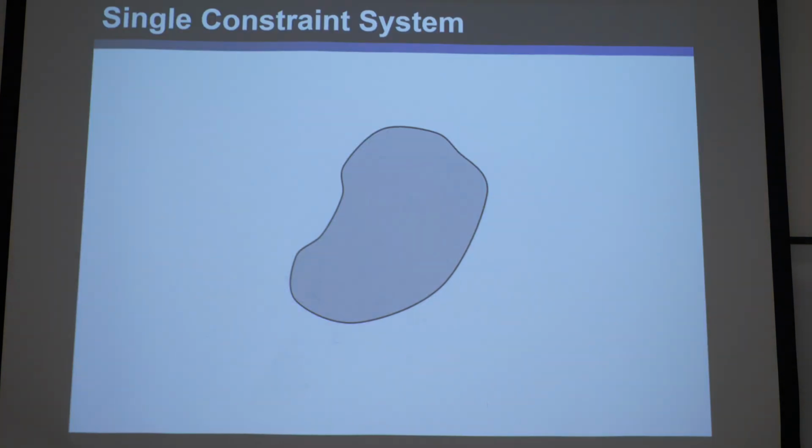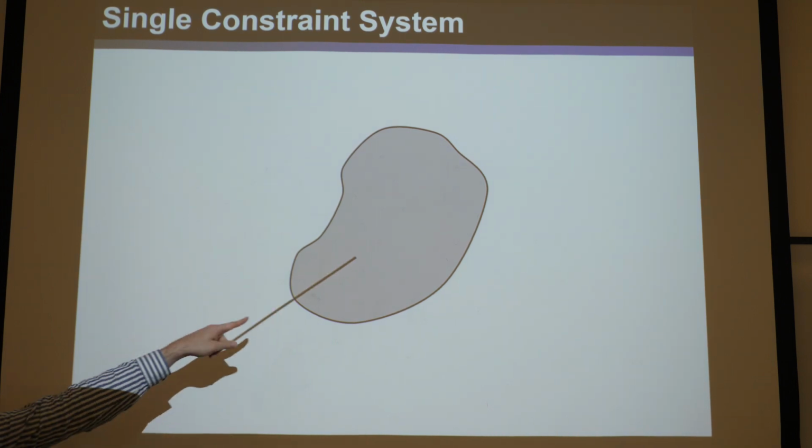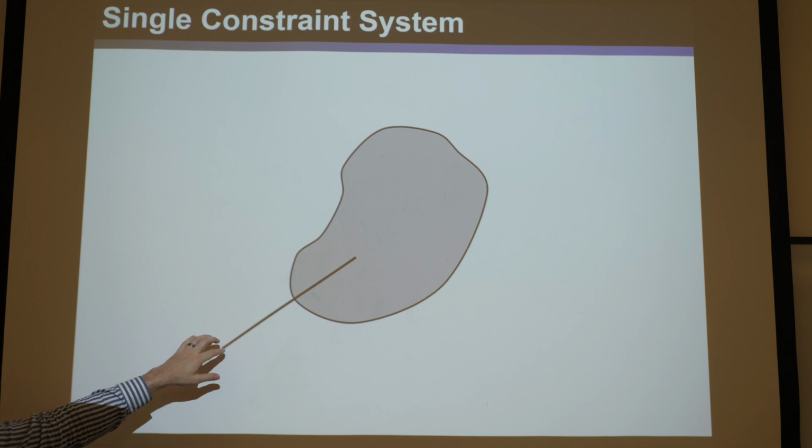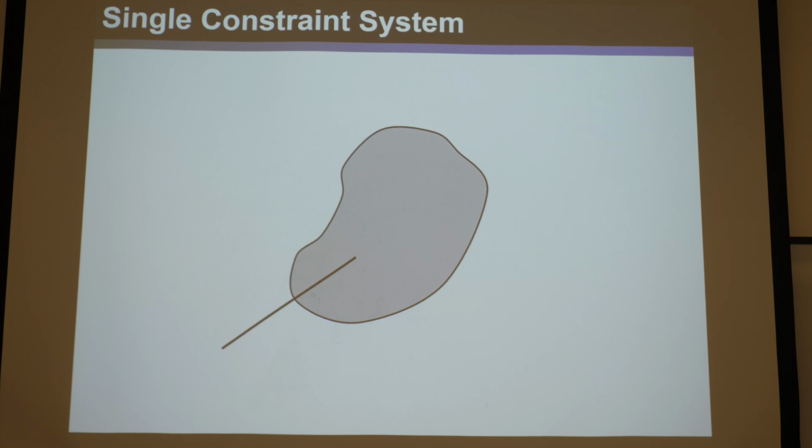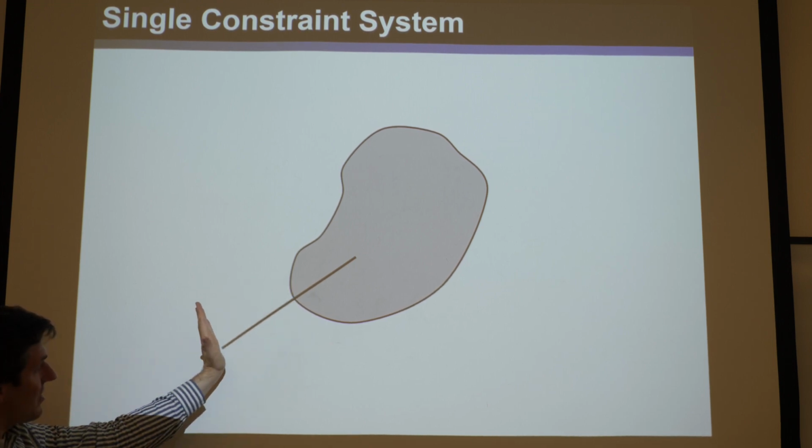Okay, so say you have this rigid potato of any shape, and say you're playing pin the tail on the donkey or something, you just randomly stick a wire into it and ground it on its back end. That would be the simplest constraint system there could be. Wire constraints are the simplest flexure constraints, and here we're only using one. If you didn't use one, then obviously it has 6 degrees of freedom, and there's only one kind of freedom space that has 6 degrees of freedom. It's just motions in any direction.